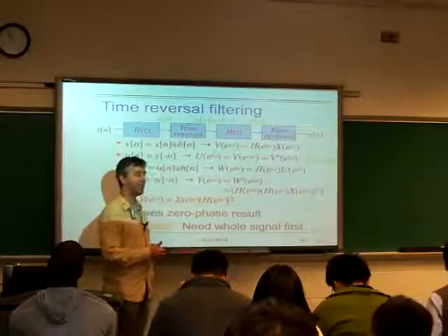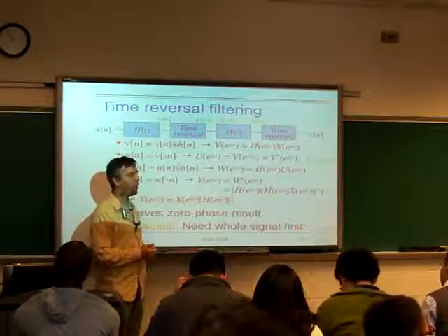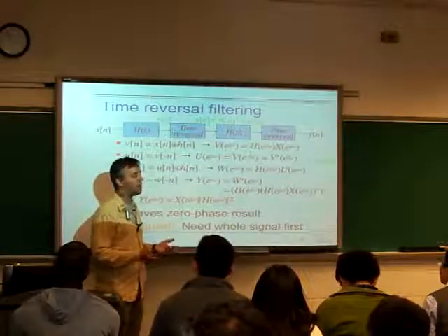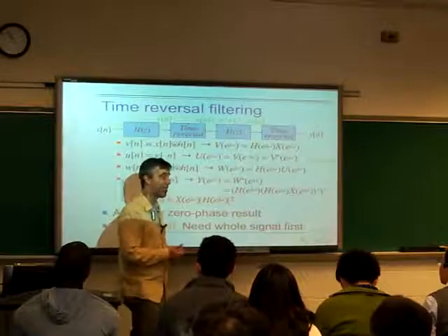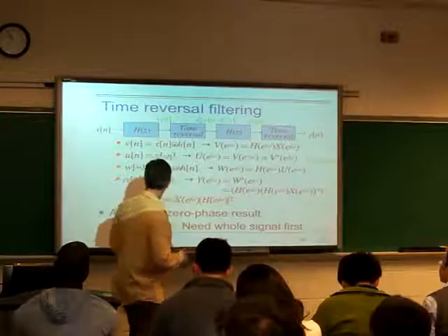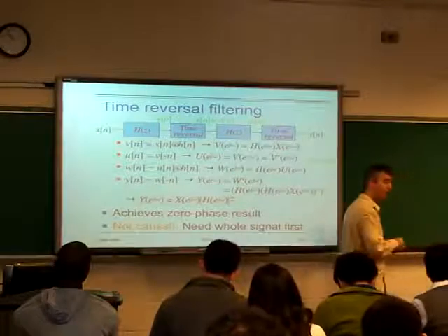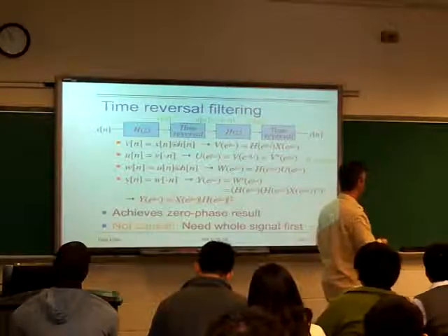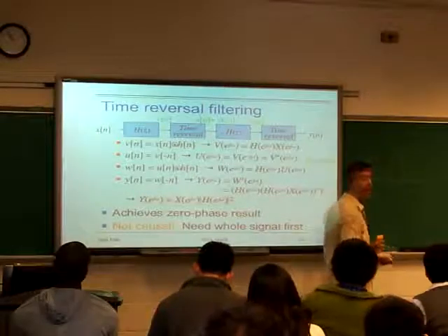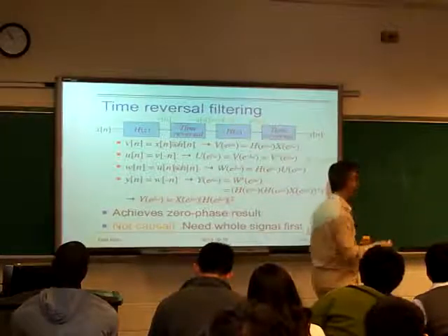Wouldn't that be difficult with actual capacitors and inductors? Typically that's not, I mean, it depends. How much harder would it be to design some magnitude response and design its square root rather than its direct form? Typically, it's not that big a deal because the magnitude response you want is some kind of thing with some passband in here. On a dB scale it might look like this. But on a dB scale, the square root is simply dividing it by 2.